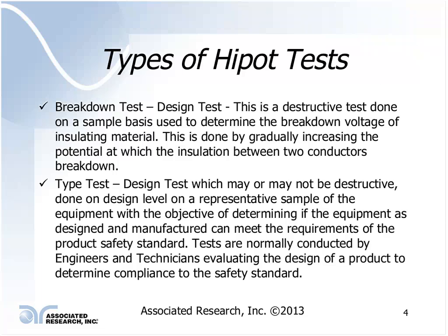But anyway, a breakdown test is in fact a destructive test. This test is not something that you want to do at the end of your production line. I don't want to buy a product that you've run a breakdown test on. It's not going to work very long. Besides that, it could create some kind of a shock hazard to the individual trying to use it. So if somebody asks you what type of Hipot test you're doing, I hope your answer is that you're not doing a breakdown test, that you're doing a dielectric withstand test if it's on a product that you're selling to other individuals.